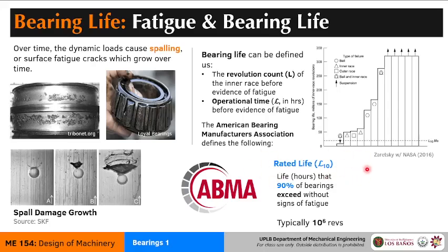When we think of rated life, of course, it's not the life of the bearing with nothing loaded onto it. So this rated life is paired with a load property. That load property is something that we call the catalog rating or the C10. The C10 is the radial load, so it's the load from the side that corresponds to the rated life.